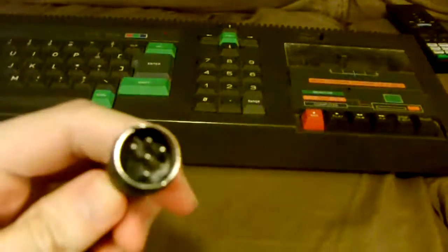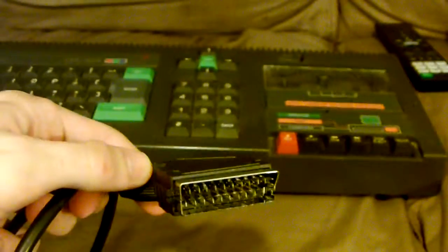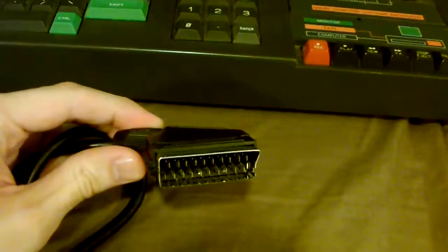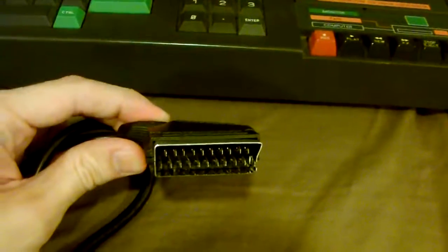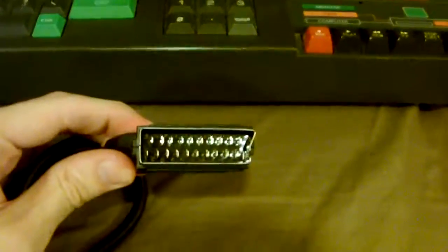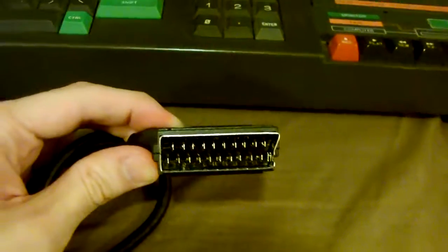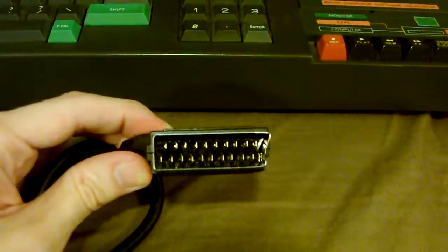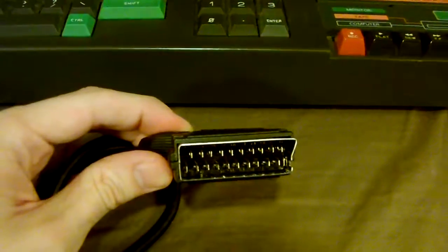Which means you can get a cable like this right here, which this end plugs into the monitor port, goes in like this, and then on the other end of that cable is a standard SCART adapter. Plug, whatever you want to call this thing. This was a very popular standard in Europe, SCART connectors. You could find it on basically everything from TVs to VCRs to satellite boxes to computers. And inside there is a number of pins, and they are all dedicated to specific functions. 3 of those pins give you the RGB, some of those pins are for video sync, and some of those pins are for audio.